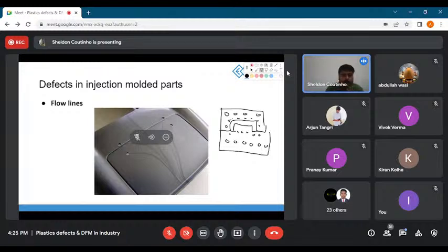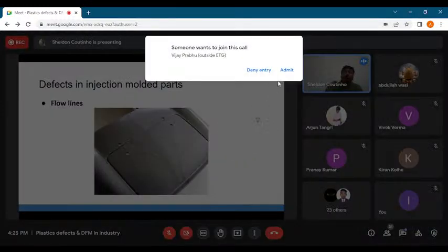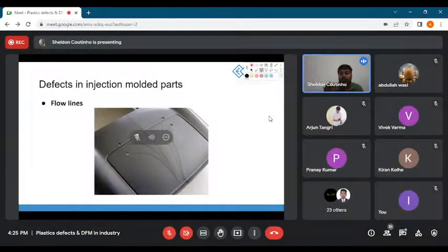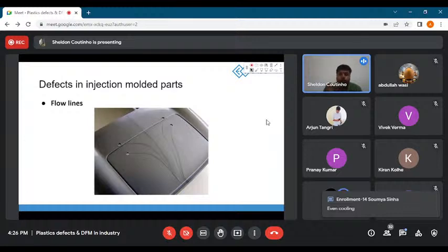Okay. Hello, everyone who has joined recently. So yes, the second thing that you can do is increase the injection speed. When you are injecting, you need to inject at a much higher speed. It already happens really quickly, but even faster, if that is possible, would be a much better alternative. And the last alternative is to ensure that the plastic is heated enough right when it is being injected. If the plastic is very close to its solidification point at the point of injection, that's when you'll have problems, and it will cool much quicker.